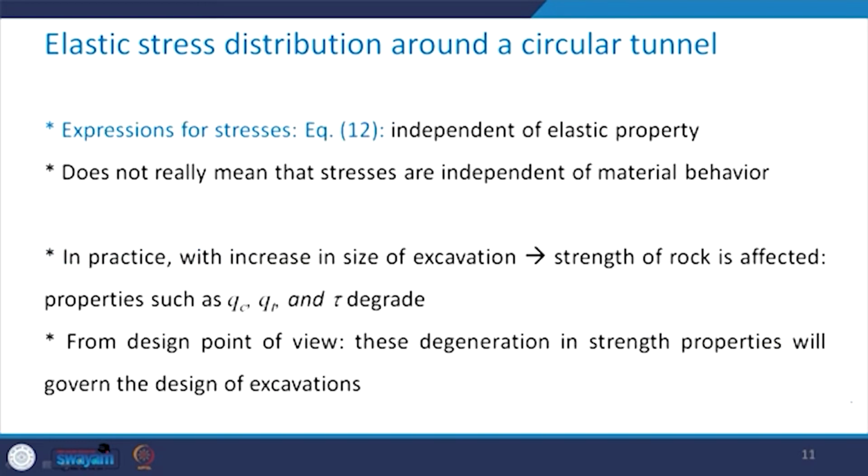Now, the expressions which were given for these stresses using equation number 12, we have seen that these are independent of the elastic properties. What were those? Like E and nu. So, those expressions for sigma r, sigma theta and tau r theta were not functions of E and nu.